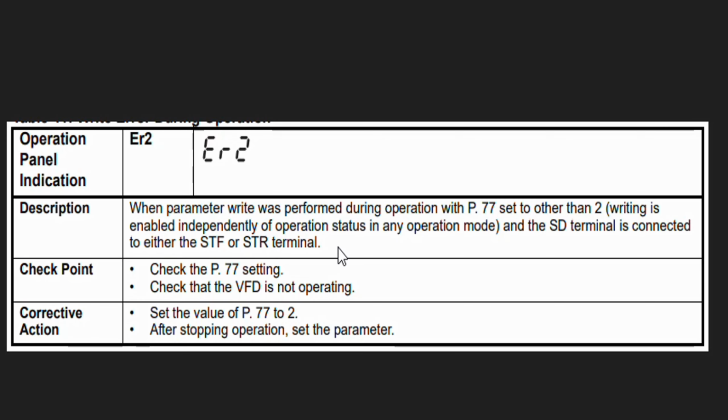So please check the P.77 setting and check that the VFD is not operating. You can set P.77 after stopping the operation, and the error will be resolved.